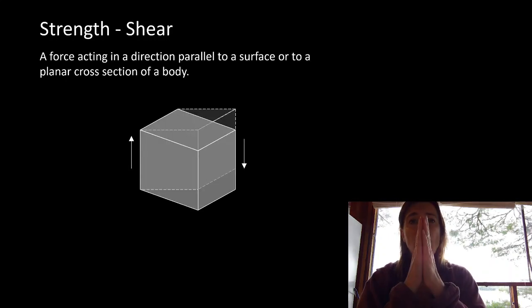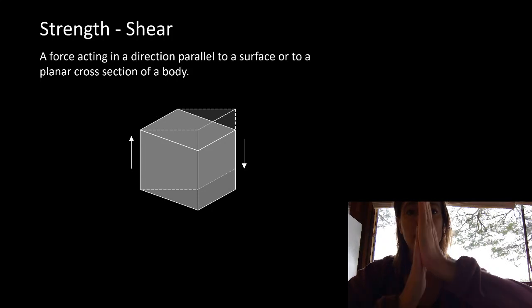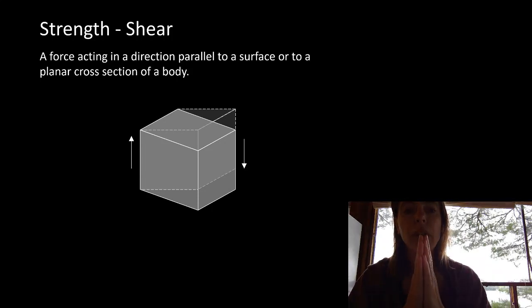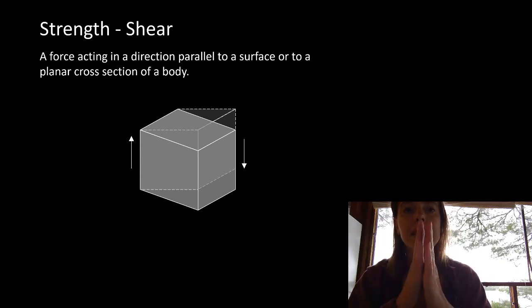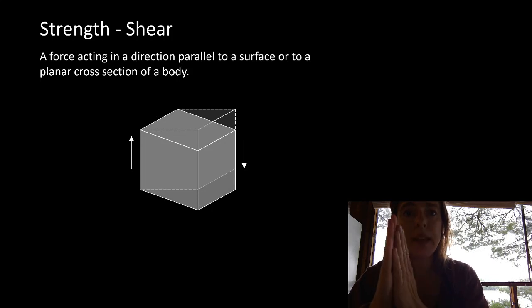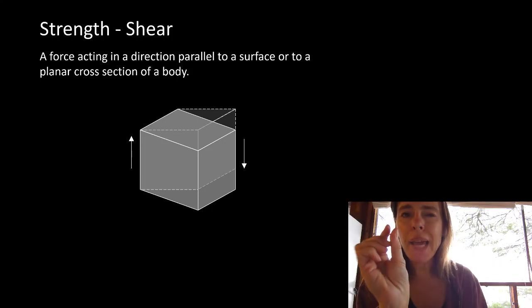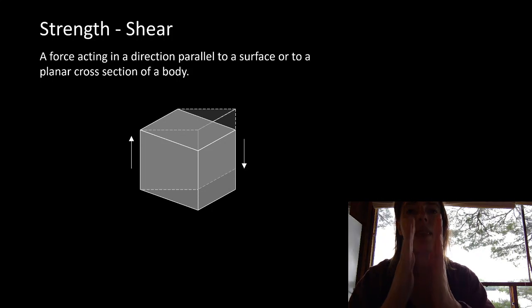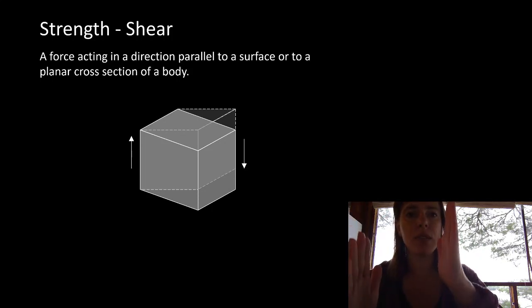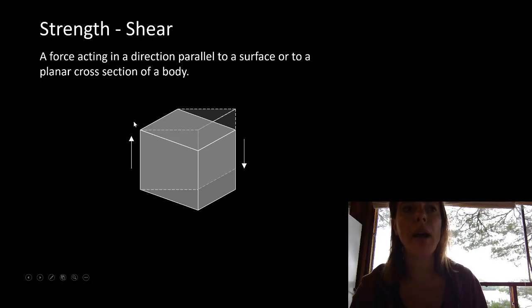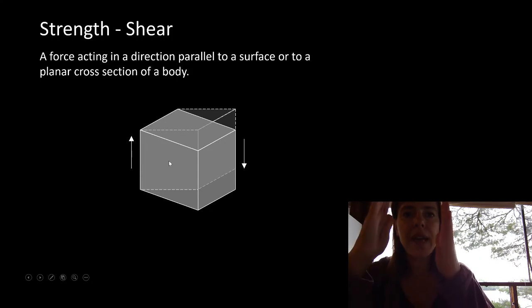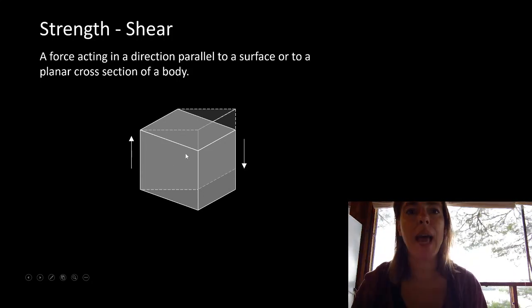Shear is talking about two planes trying to slip relative to each other. You can see that the drawing here has those two things pulled apart. It's still just this plane trying to slip past the next plane, and the next plane, and these are a micro distance apart from each other, and the aggregate of all of those things trying to slip past each other gives us this kind of elongated form here where it's turned our square into a triangle. That starts to be the way the movement happens in a system.